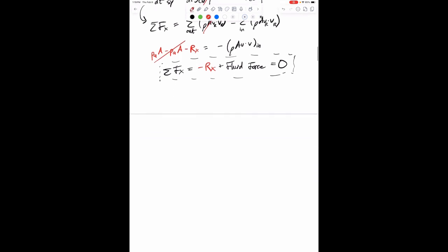Okay, so reaction force is equal to negative rho. Rho is, I believe, given as 1,000 kilograms per cubic meter. Your area, the jet nozzle area, was given to be 3 square centimeters. We want to work in meters, so we're going to divide by 100 squared to go to square meters, times resultant velocity squared, because there's 2 of them. So 5 meters per second squared.